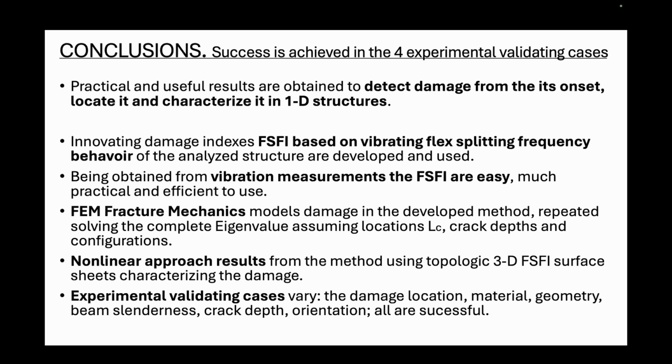They are obtained from vibration measurements, which are very easy and practical to use, also in very high cycle fatigue, because very high cycle fatigue is actually based on vibrations. Finite element fracture mechanics are used for the development of the models, and the nonlinear approach results because of the topology of the surfaces.